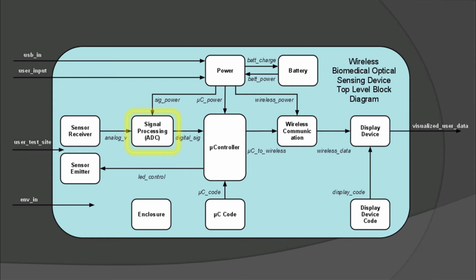It does this using an ADC, or analog to digital converter. Depending on signal quality, it's possible that the onboard 12-bit ADC built into the microcontroller can be used for data conversion and collection, simplifying the design overall. If it is unable to do the conversions with enough quality and speed, an external low-noise ADC may be used with the same 12-bit resolution.